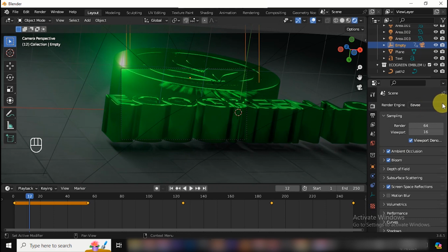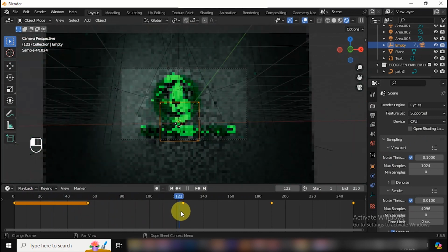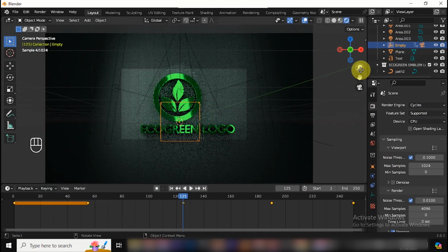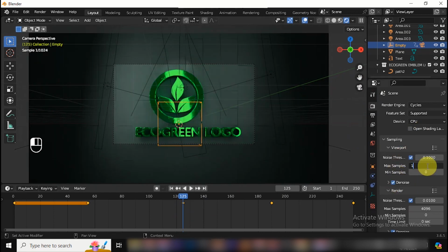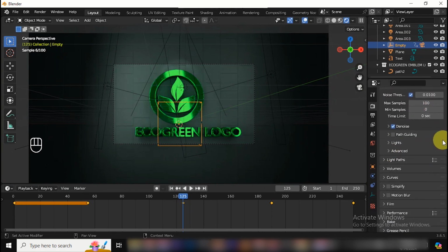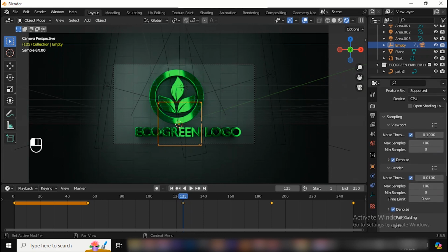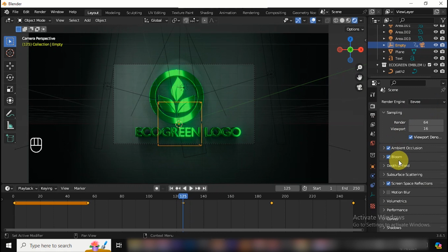In Blender, there are several render engines available, each with its own set of features, rendering techniques, and capabilities. For instance, Cycles has realistic rendering and supports advanced features like ray tracing, volumetric rendering, and GPU acceleration. I will not use it due to its computational intensiveness and slower rendering speed compared to real-time engines. Let's continue using Eevee for the final render due to its fast rendering speed, straightforward setup, and configuration.